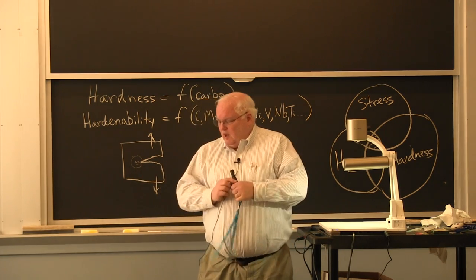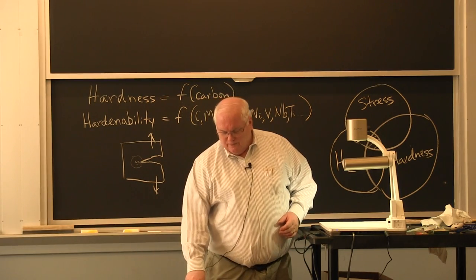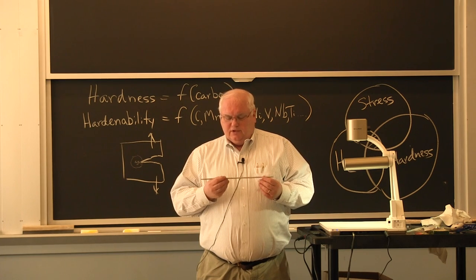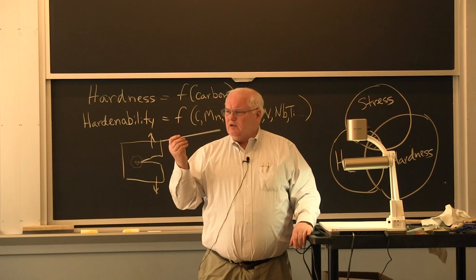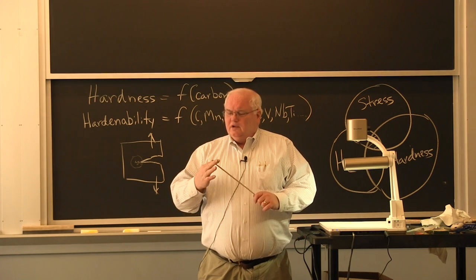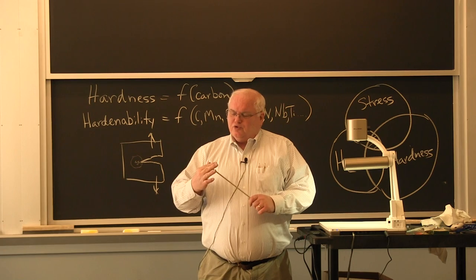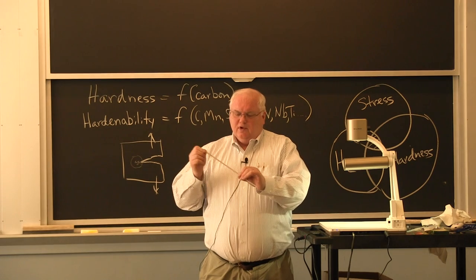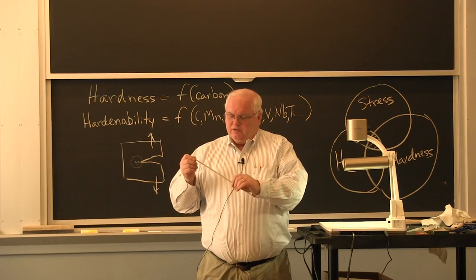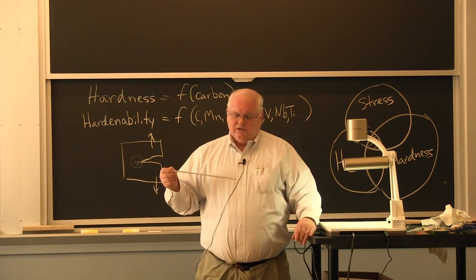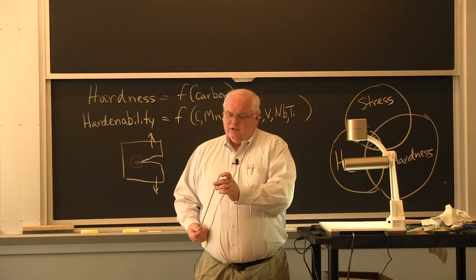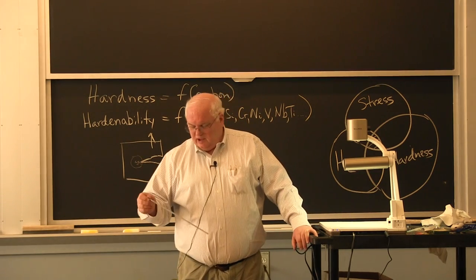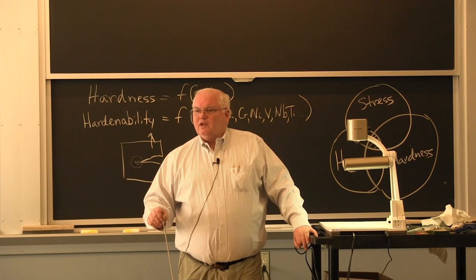Okay, so one of the common things, and we'll talk about it some more, are stick electrode coatings. Stick electrodes are still used. Back 40 years ago, 60% of all welding was done with a stick electrode. You take an electrical copper clamp, you clamp the electrode on this end where it has no flux coating, which will melt off and form a slag to pull out the impurities and protect the weld. It has a tip that's been brushed off so that you can strike an arc if you have a helmet on, hopefully, so you don't sunburn your eyes.